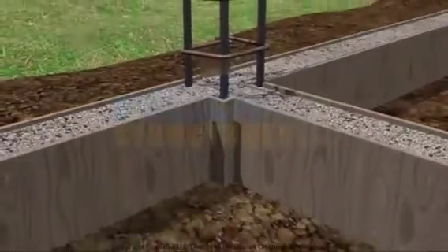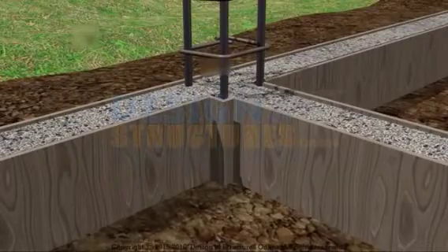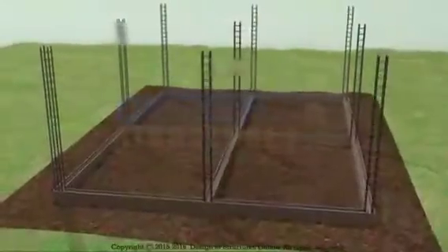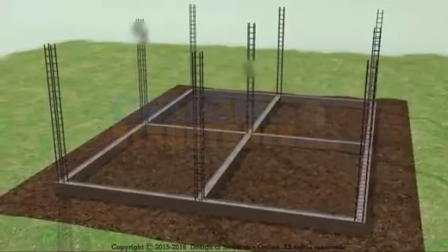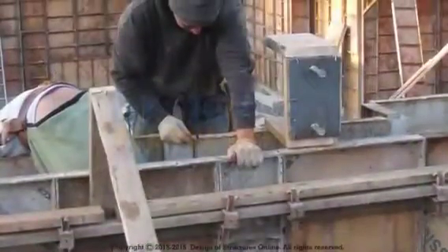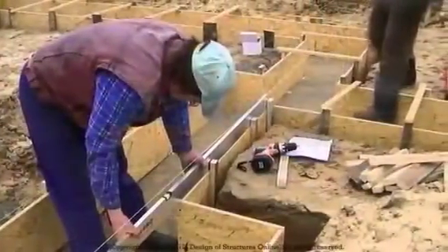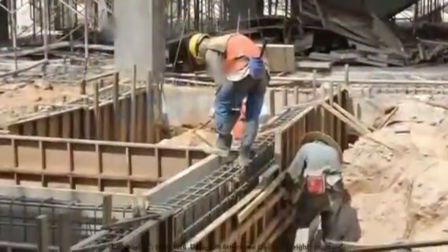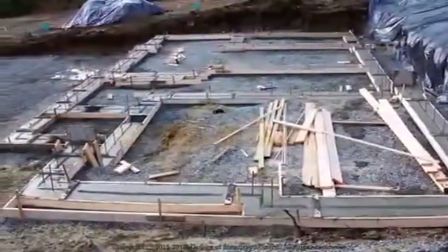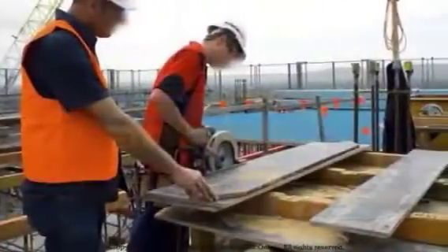Beam concreting. Beam is poured with concrete with the grade mentioned in the drawings. The positioning of reinforcement should be properly aligned. Shuttering parts and connections should be arranged in a way that makes formwork removal easy and simple, prevents damage to concrete and formwork panels so that they can be reused without extensive repair.